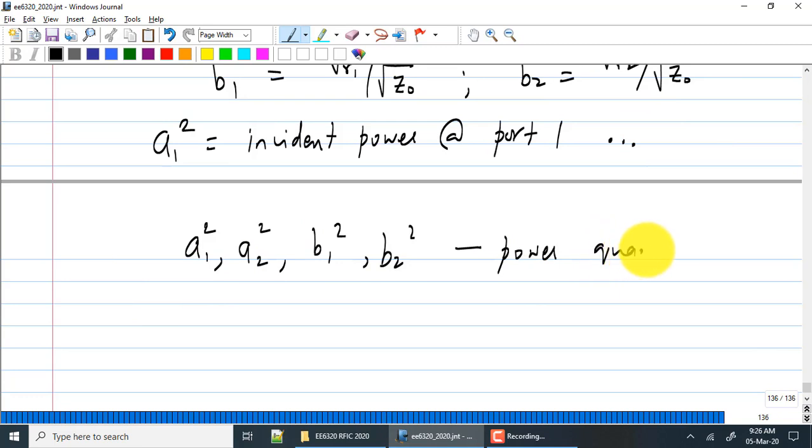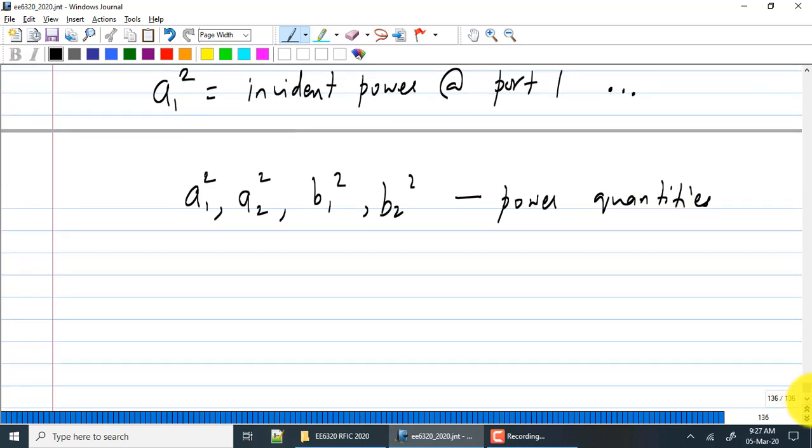And in general, in microwave theory, you will find that you talk mostly in terms of power because the standardized impedances are all 50 ohms. So you always deal in terms of power, right? So much power is incident, so much got reflected back, so much got pushed into the system. When you deal with two-port systems, you talk about power gain of the two-port and so on, because you're talking about matched impedances at input and output. This is a quick introduction to S parameters.